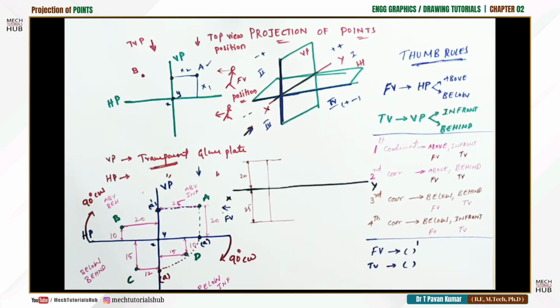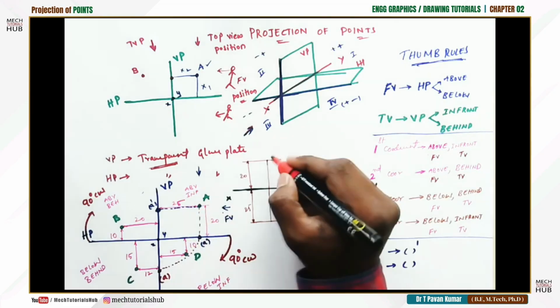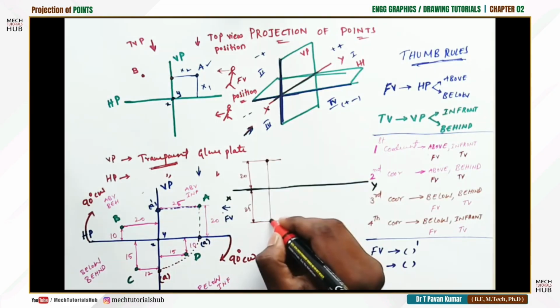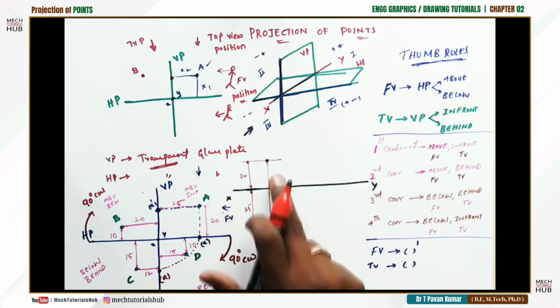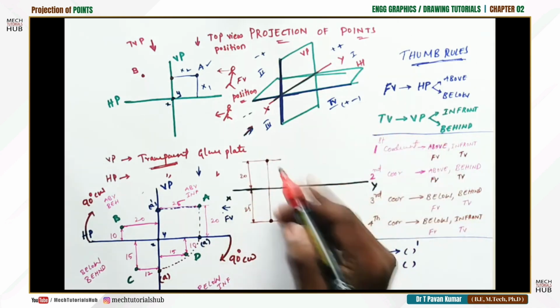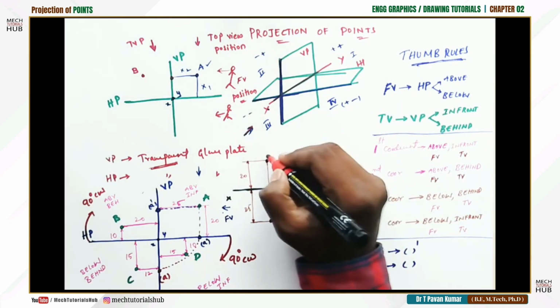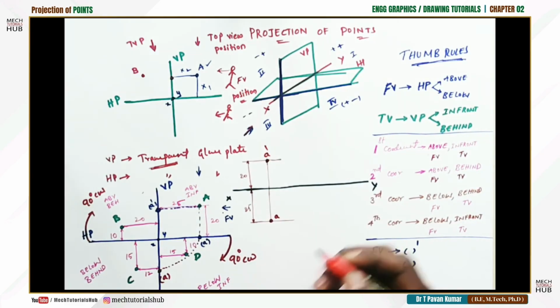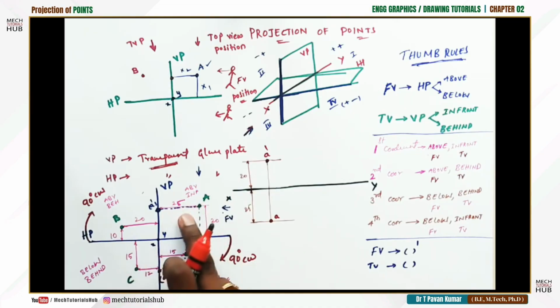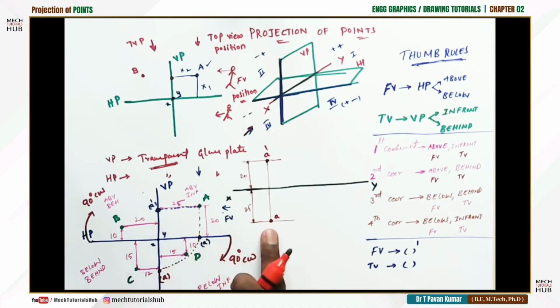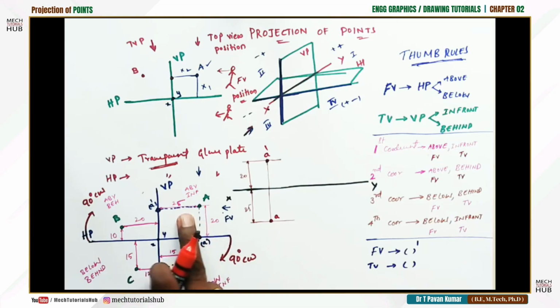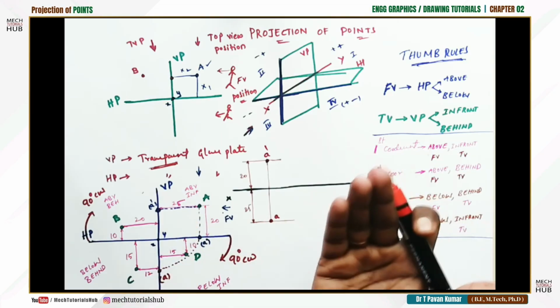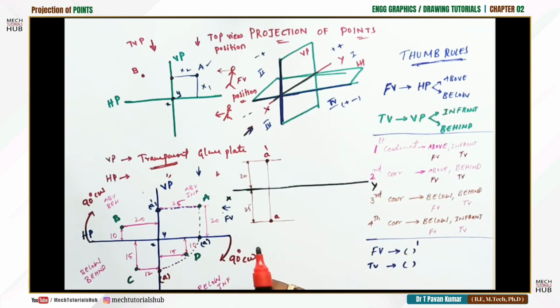Once it has met the 25 mm line, take an HB pencil. Our intention is to show the projection of an object. Here the object is A. It is only a point that needs to be highlighted. Fine. Now here this is your front view. Above is your front view, so you can call it A prime. Below is the top view. You can call it simple A. Front view, top view. So we are dealing with the first quadrant. In the first quadrant, we can make one more conclusion: front view is always above the XY line and top view is always below the XY line.